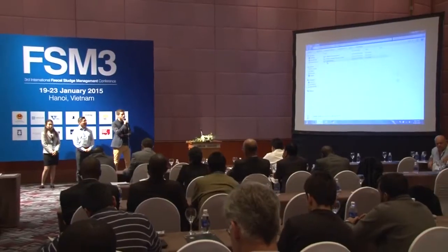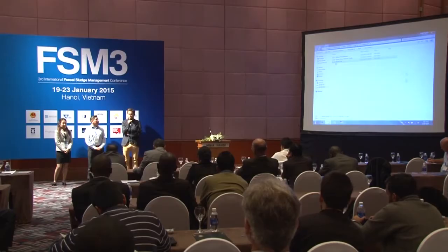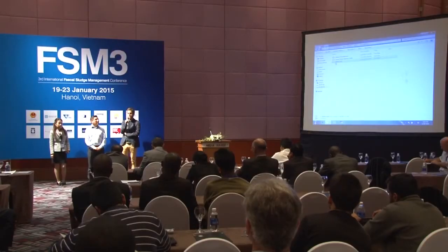You're right, the selection of the commercial products is very difficult. If you call up one of these companies, they ask you what sludge you have. Is it industrial? Is it a mixture of the industries in your catchment? Is it simply domestic? They talk about wastewater sludge. And I simply couldn't tell them a lot about the sludge I have. I could tell them it's septic tank sludge from Dakar. If you call up a French or a Swiss company in this case, they can't really tell you what product you should use, because conditioners are commonly used in wastewater treatment.